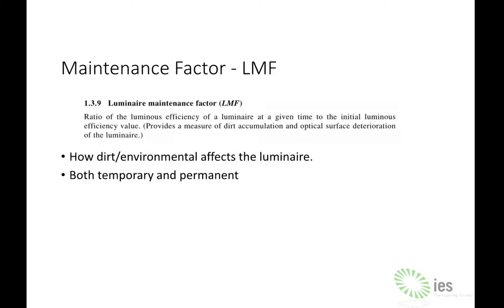LMF is basically how the dirt or the environment affects the luminaire. It consists of a temporary component, like dust on the lamp itself, which can be wiped off quite simply, whereas a permanent component might be pitting of an optical surface, and that is a permanent degradation of the luminaire source.